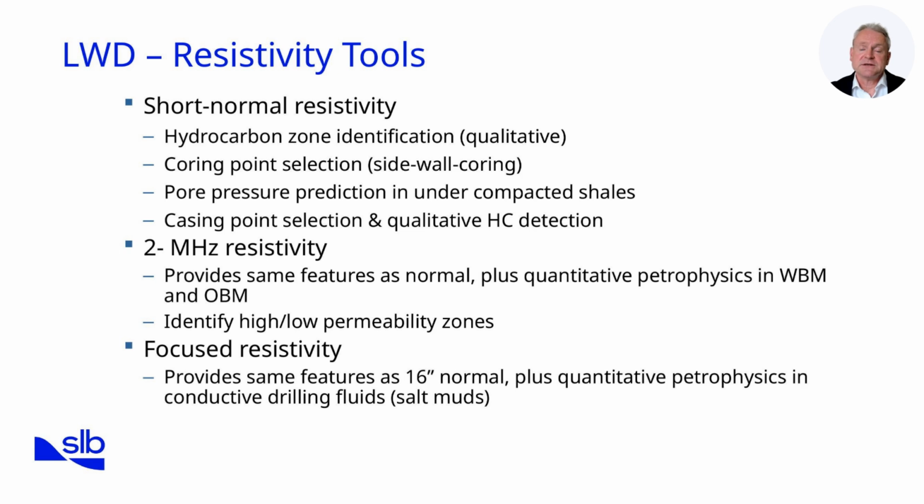Finally, the focused resistivity tool. This works in a similar way to the 16-inch normal resistivity measurement, but is designed to work effectively in conductive drilling fluids, such as salt-based muds.